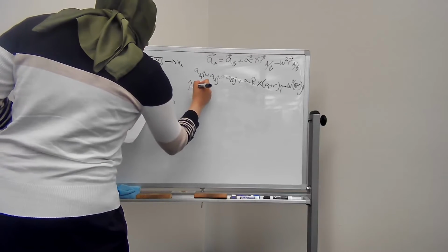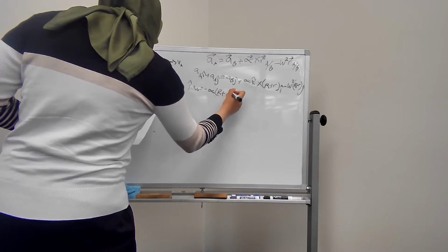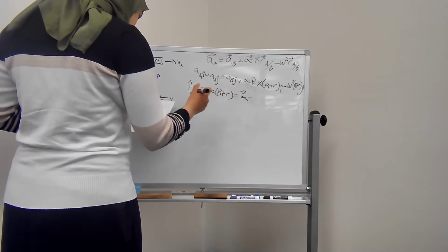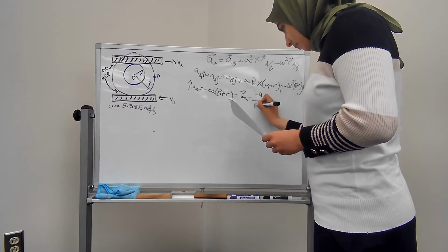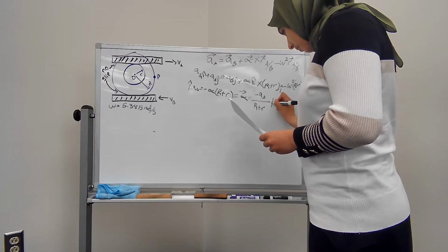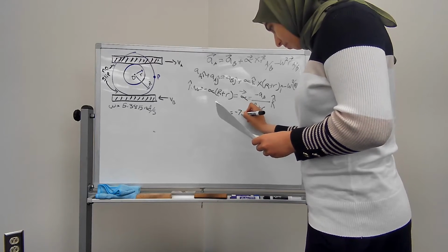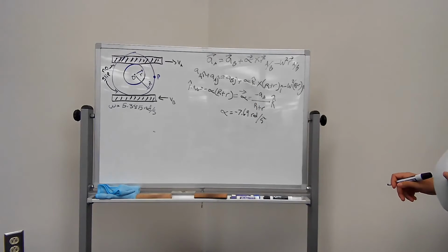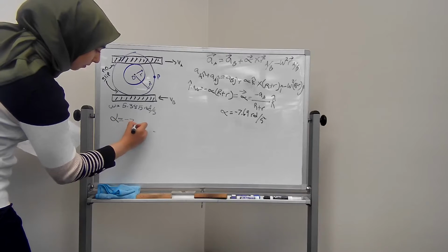Since we know all of the values that we need for this equation, we can solve for alpha using the i component of the entire scenario. And we can get that alpha is equal to the negative acceleration at A in the i direction divided by the quantity big R plus little r. And once again, just to check our work, the numerical solution that we got is that alpha is equal to negative 7.69 radians per second squared, and that would be in the k direction.